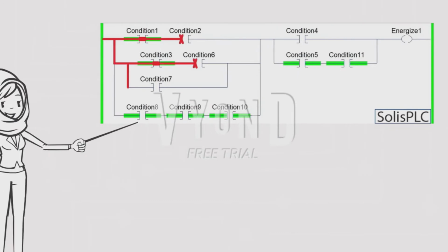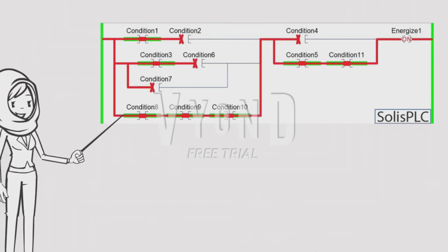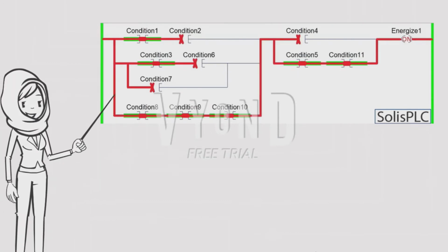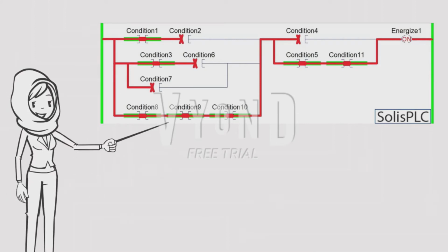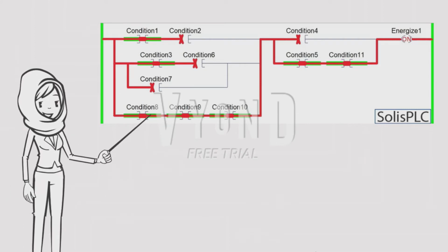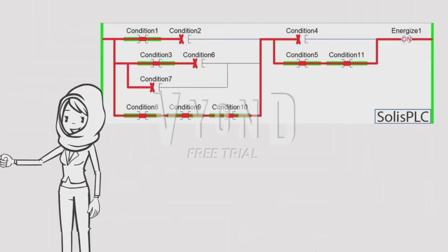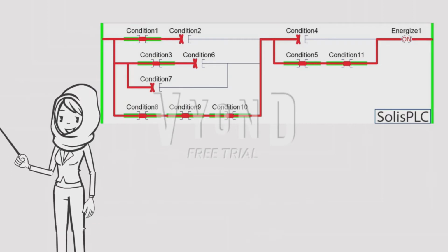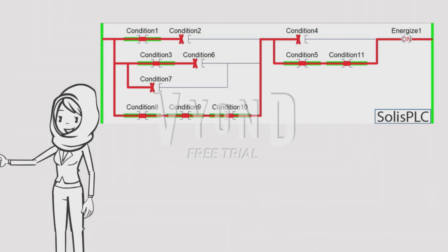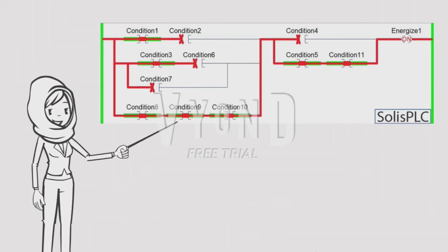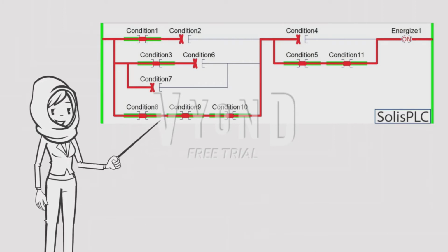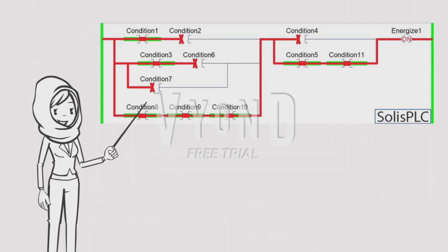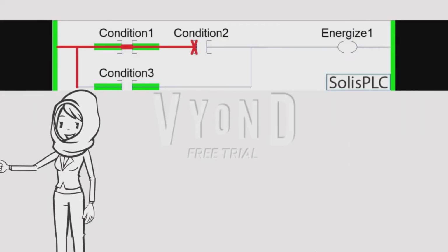In order to learn ladder logic diagram, to identify the flow of current is crucial in terms of where is the path that the current will take. Firstly, when the power is on, current starts from left to right rail and it will attempt to flow through one rung at a time. When it encounters an input condition, it will identify if the result is true or false. If the condition is true, the current will execute the instruction. If it is false, the current will go to the next rung. And here is an easy example.